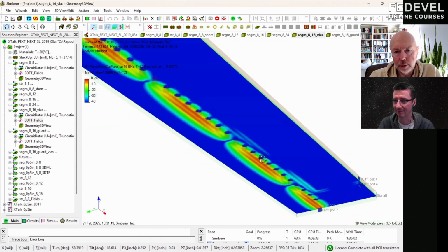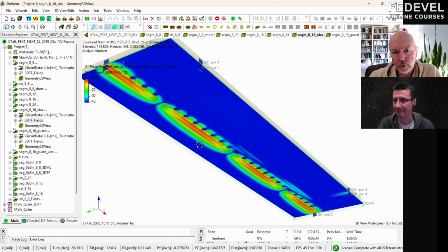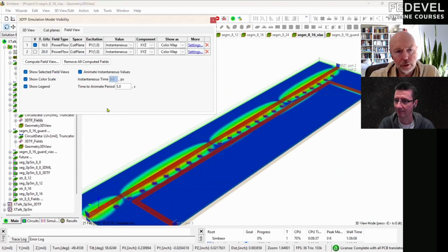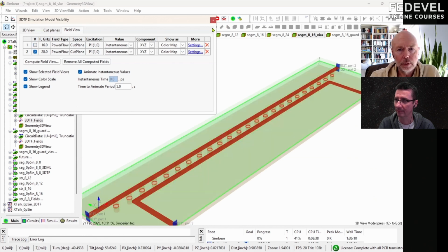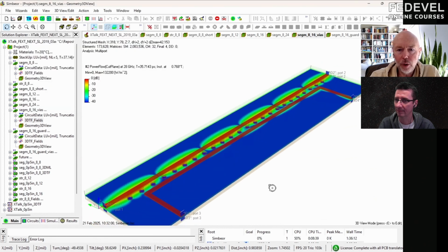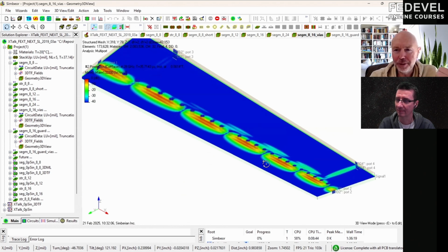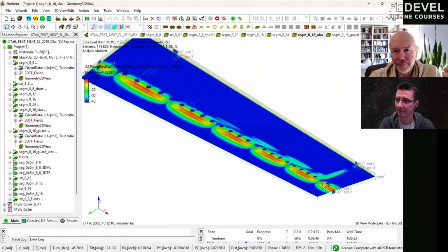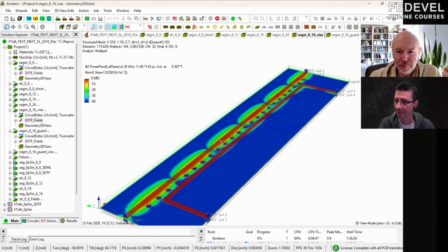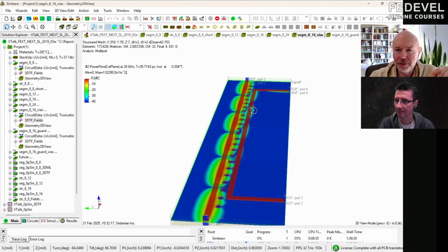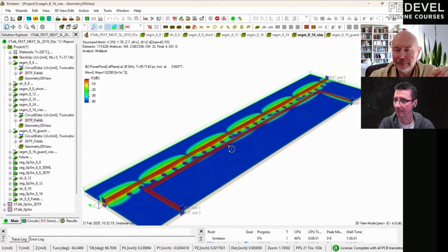It's a beta coupler, so-called. And again, if we increase the frequency, we can see how well this coupler works. And this is a fine coupler. So that's how we create this: make a lot of small holes between two waveguiding structures, and then the energy gets into the other.